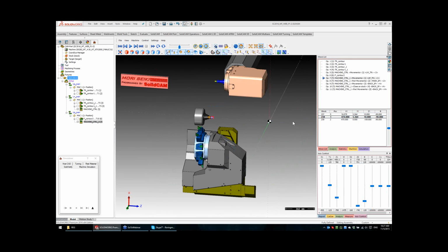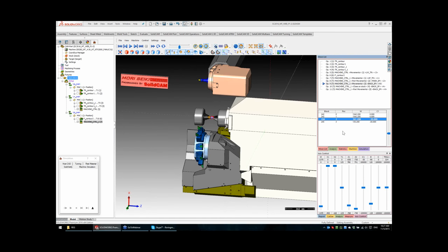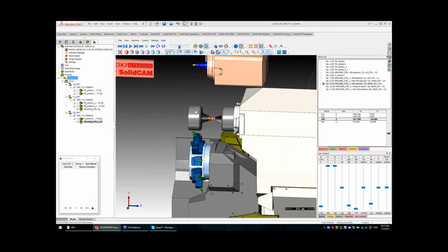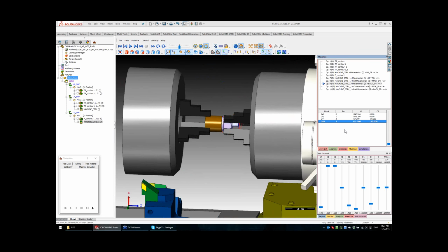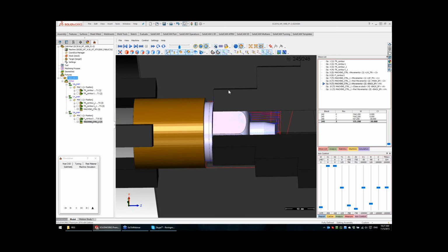I start the transfer process. Upper turret retract to a safe position. Lower turret is already in a safe position. Back spindle entering in the milling mode. C-axis to 0, and W with rapid to this position. Catch the part exactly where I want to catch the part on the surface.